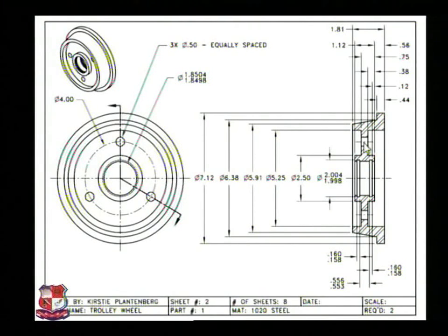Both these holes are visible in this view, and this is important where an odd number of holes are there. If an even number of holes are there, it may not be needed, but as 3 holes are there, we need to draw this kind of inclined cutting plane.